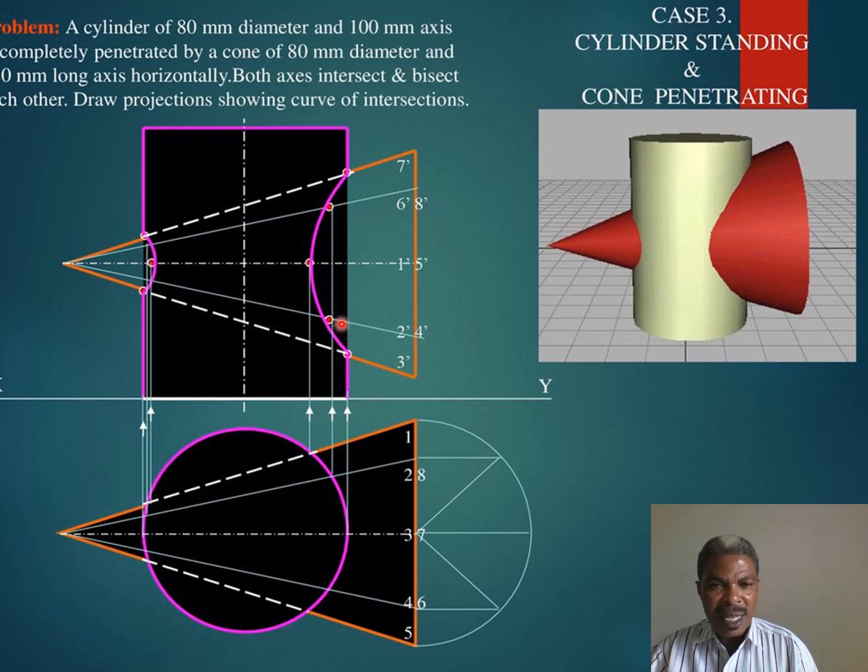This same line here, if it was number 2, for example, from the same circle here, number 2, then projecting to the apex of the cone, but in between it has intersected the surface of the cylinder. So here is where we get the changing of direction, going upward until it meets another line of number 2 from the same circle. This is our point of interest.